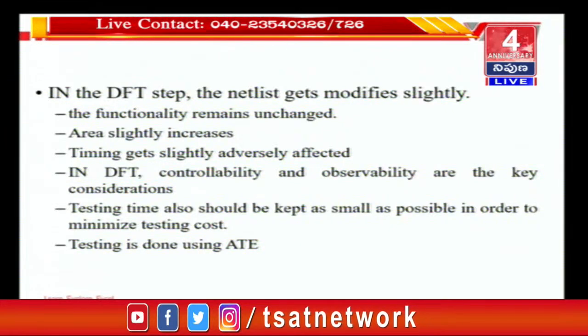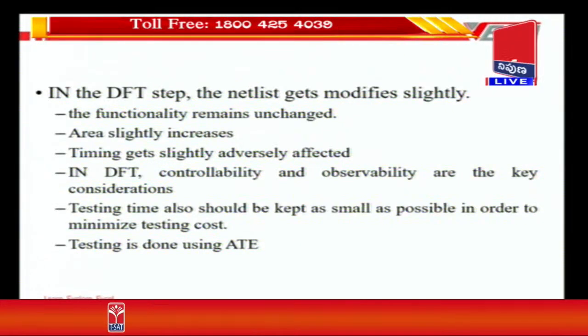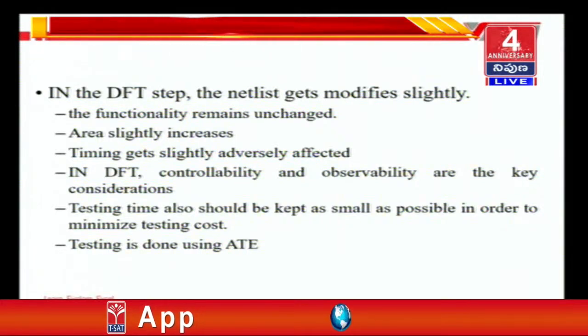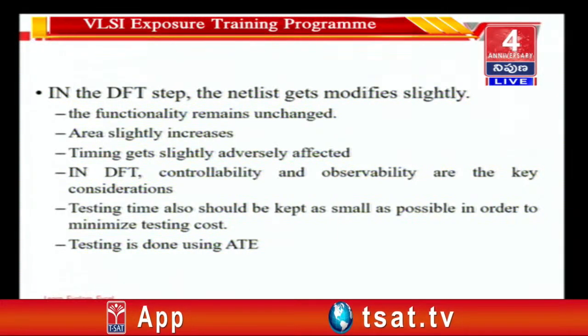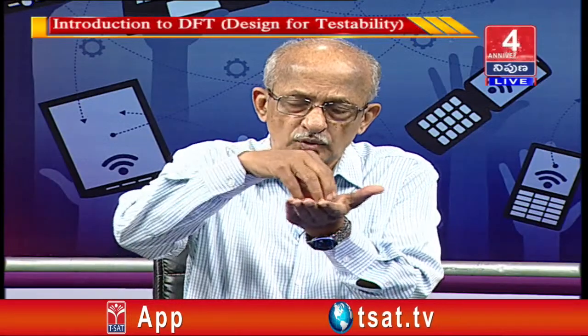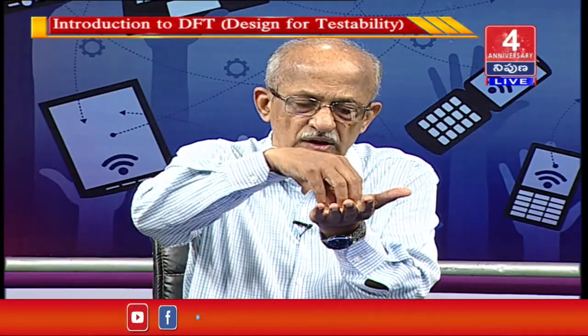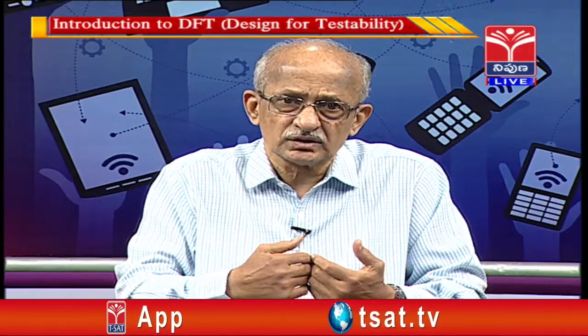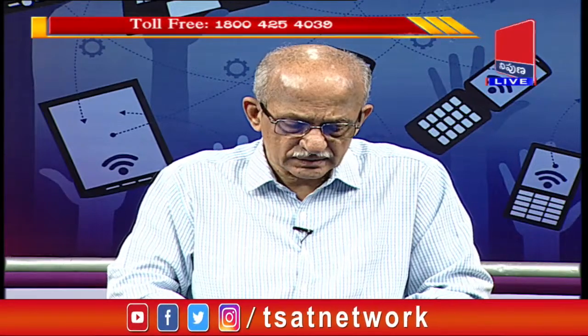Testing is done. Now, when you have a tester, the tester applies the patterns to the chip through the probe, which I told you sits on the chip on the wafer and applies the test patterns. The probe has got a cable, which collects the response, and the response is analyzed by the test equipment itself, and then it will say whether it is as per the expected pattern or not, and then it will declare whether that vector is passed or not. So, this is how it will be tested.